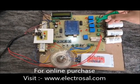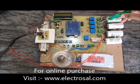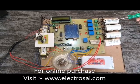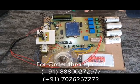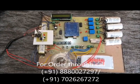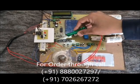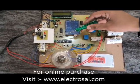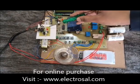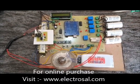We have also used a relay driver IC to safely interface the Arduino with the relay module. The relay controls a shunt capacitor bank which is used for automatic power factor correction. An LCD display is provided to show the time lag between voltage and current along with power related parameters. Other supporting components include transformers, resistors, diodes, switches and the load lamp, with the ESP8266 Wi-Fi module to interface with IoT platforms such as ThingSpeak.